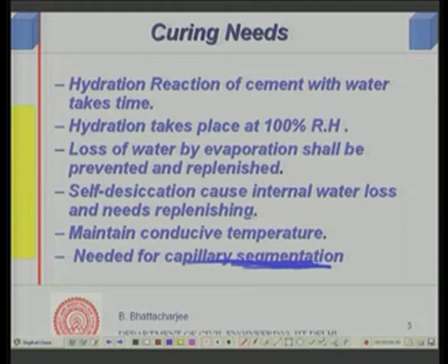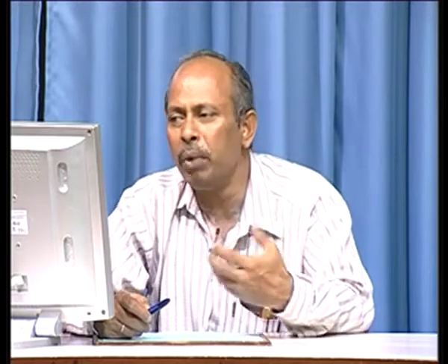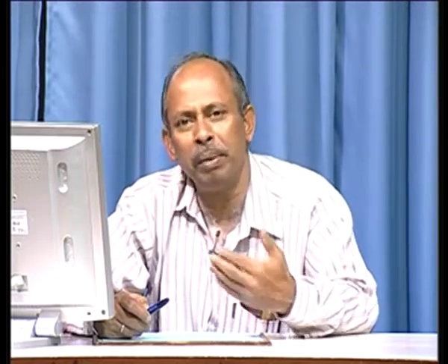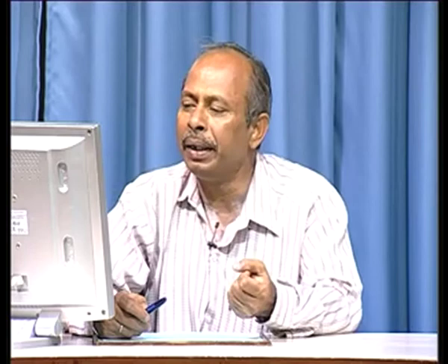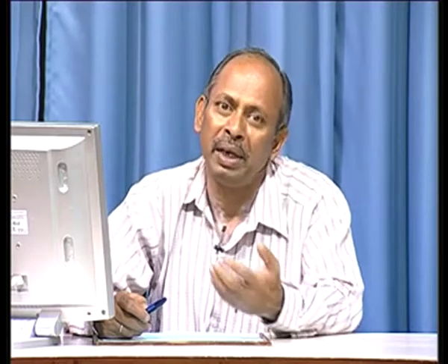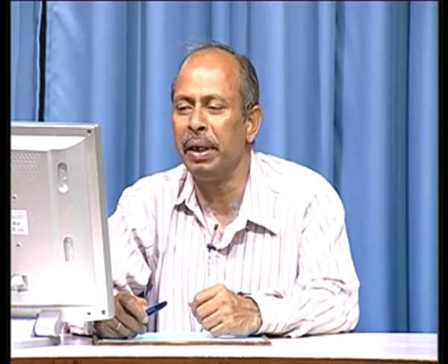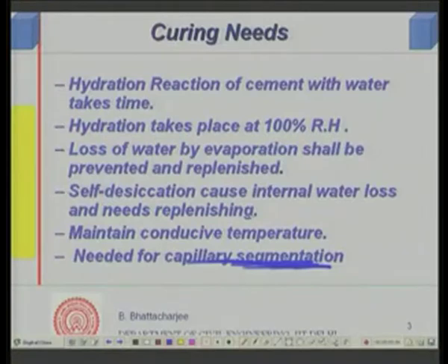So, as you can see, for strength development, curing is necessary to prevent loss of water, and in the process the hydration reaction will take place, and this will ensure that capillaries are segmented and strength development and properties development of concrete is possible. So, that is the need and importance of curing.